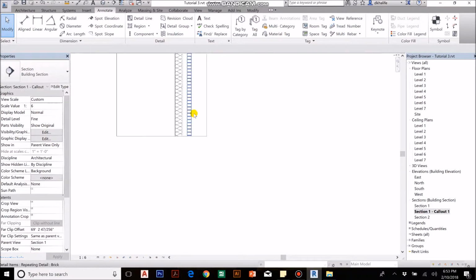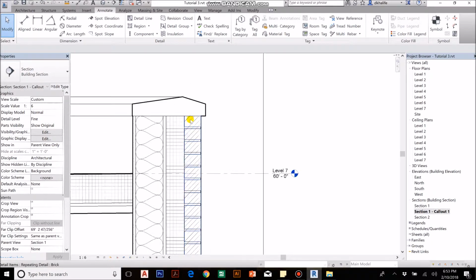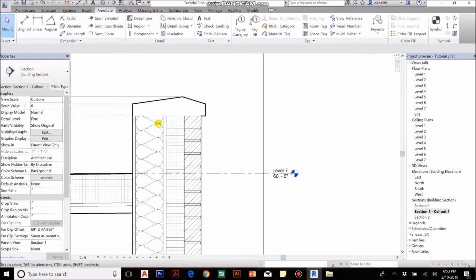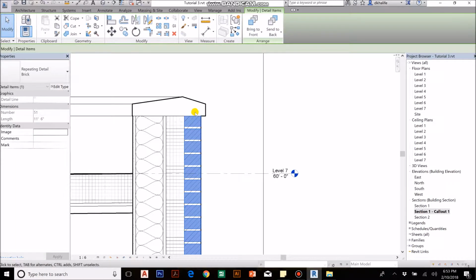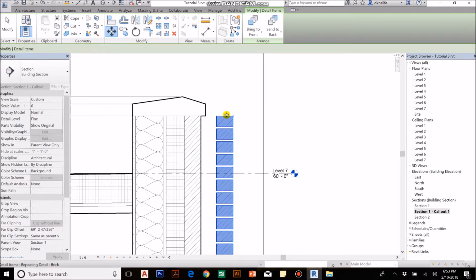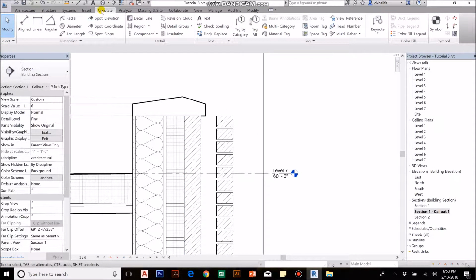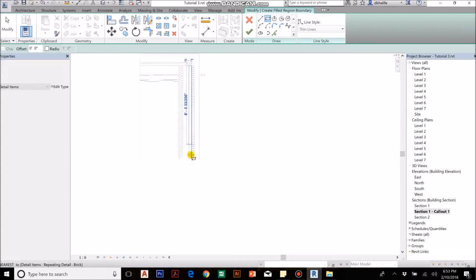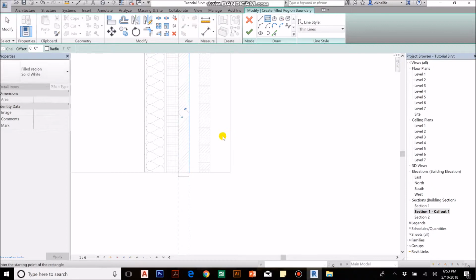So what I'm gonna do basically, instead of hiding my wall, because I don't want to, I still need the other elements in there, they're important to me. So I'm gonna add a layer behind the brick, which is white. I'm gonna move this one, MV, I type MV, move, and I'm gonna go to annotate, region, filled region, and I'm gonna draw a rectangle, a solid white rectangle.